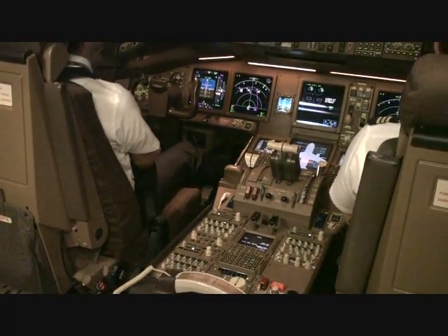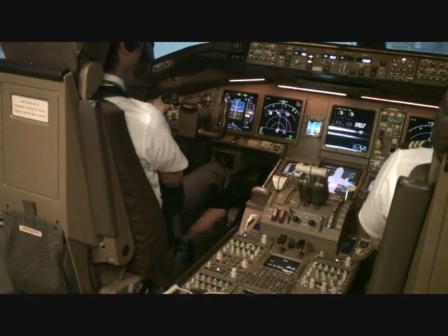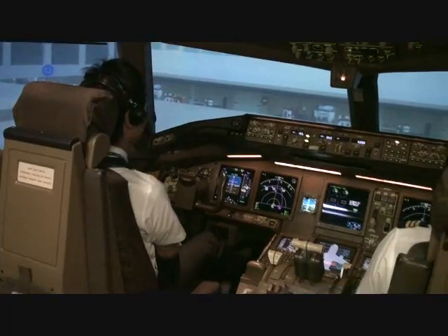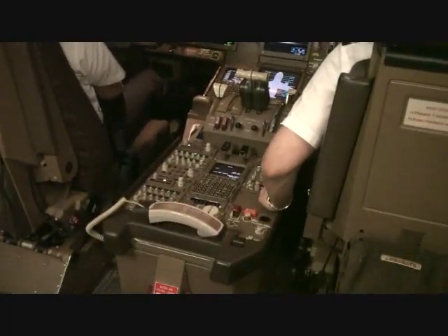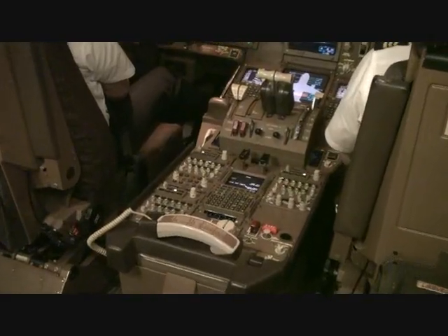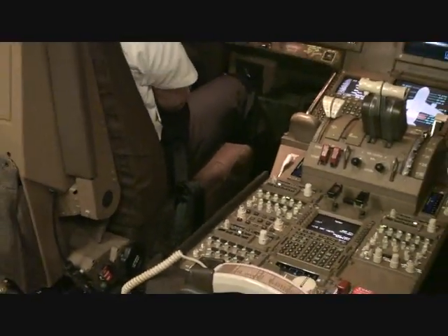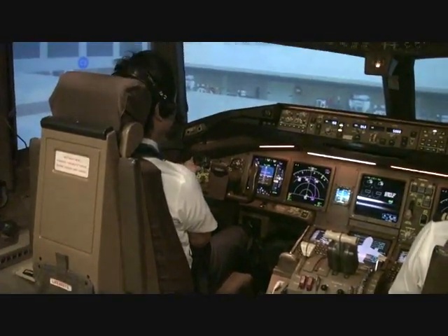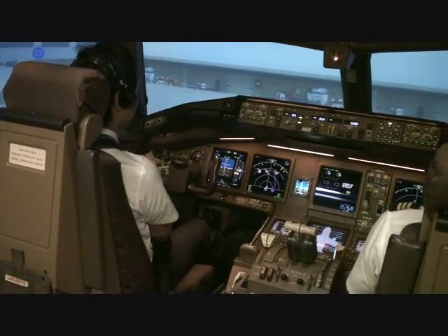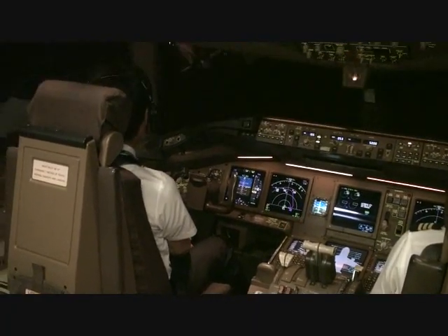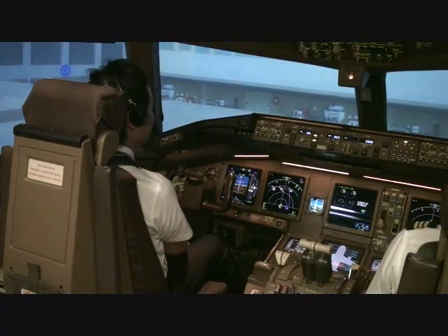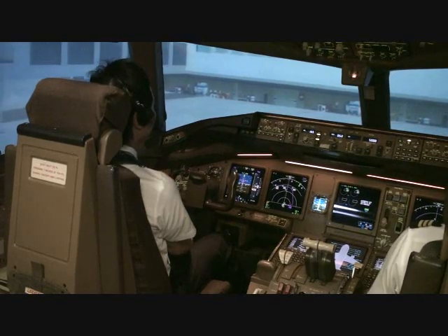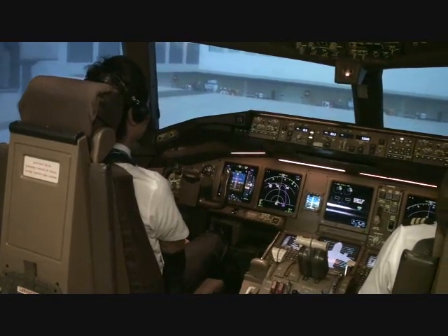Caution, do not use airplane brakes to stop the airplane during pushback. This can damage the nose gear or the tow bar. Transponder to transponder, XPDR position. Parking brake as required, in this case off. Commencing pushback, Captain. You're cleared to start engines during the pushback. Clear to start. When the pushback is complete, tow bar, verify not connected.